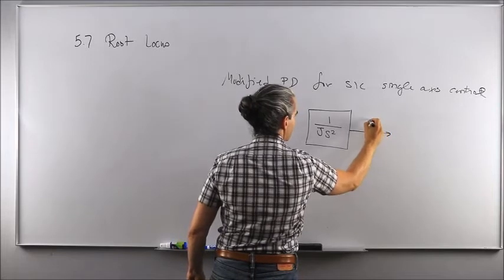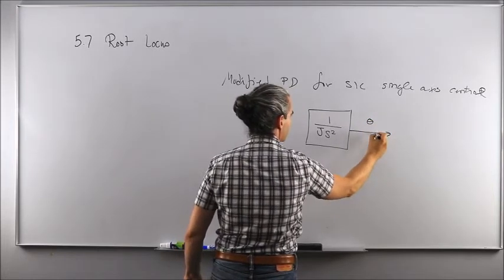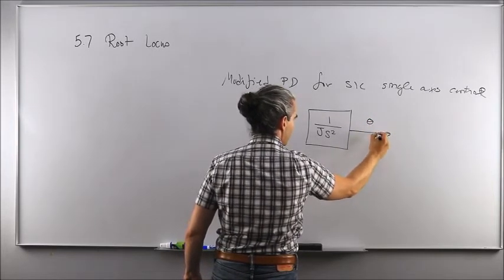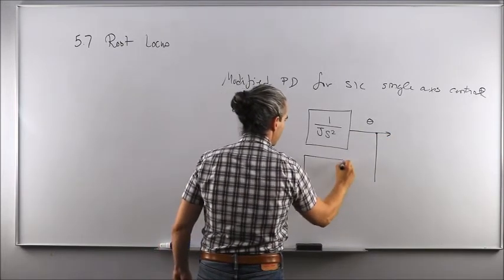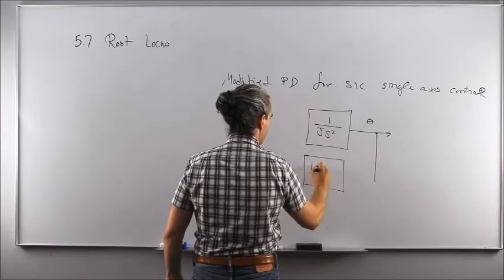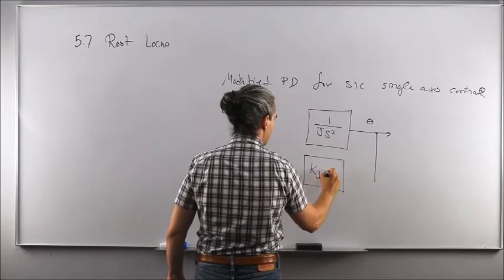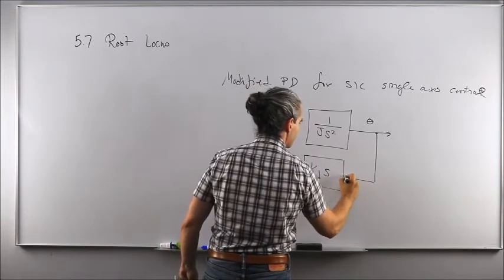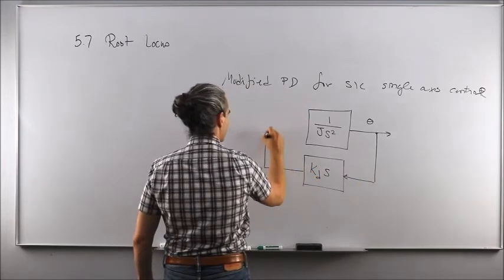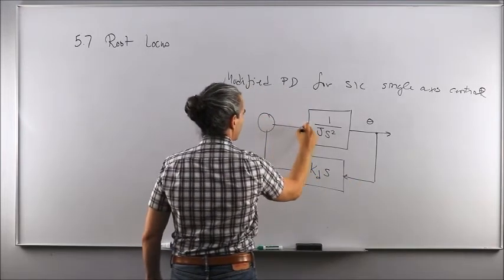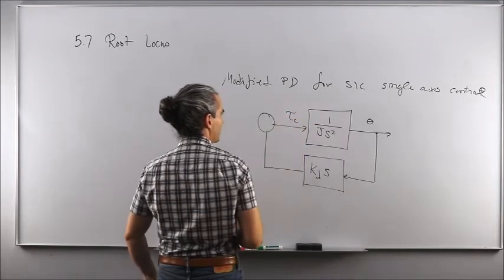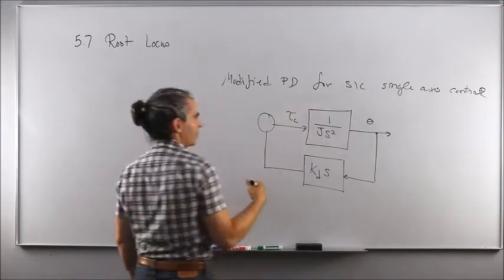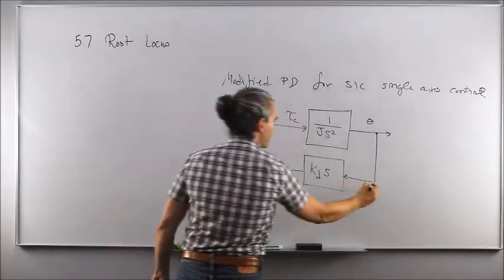And this calculates the actual angle of the spacecraft, which is spinning about a single axis. Here we have the derivative component of the controller, Kd times s, like this. That would be the net torque applied to the spacecraft, control torque as opposed to perturbation torque.